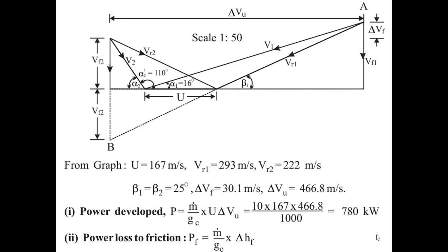Okay, sir. So if you draw 110 degrees from the blade motion U, this is not alpha 2, correct? This is alpha 2 dash. Yes, fine, sir. For alpha 2, what they have done is 180 minus 110, so they have taken alpha 2 as 70 degrees. So if this is with respect to alpha 2, then alpha 2 dash means it is V2. Okay, sir. This is challenging. If this question comes, you definitely have to solve it through these different, confusing challenges only.